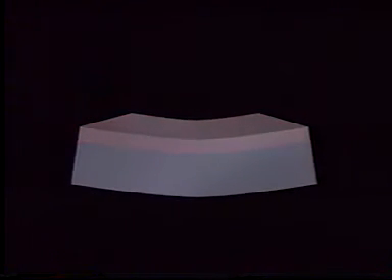Another aspect of thermal residual stresses that should be kept in mind is the distortion that can occur in a part with heating. For instance, if the upper part of the metal is suddenly heated, without significant transfer of heat to the lower section, the part can bow. The heated surface tends to expand, but is restrained by the cooler, stronger metal below the surface. At that moment, compressive stresses are formed on the convex upper surface. As the surface cools, the part bows. This is very common during welding and heat treating.